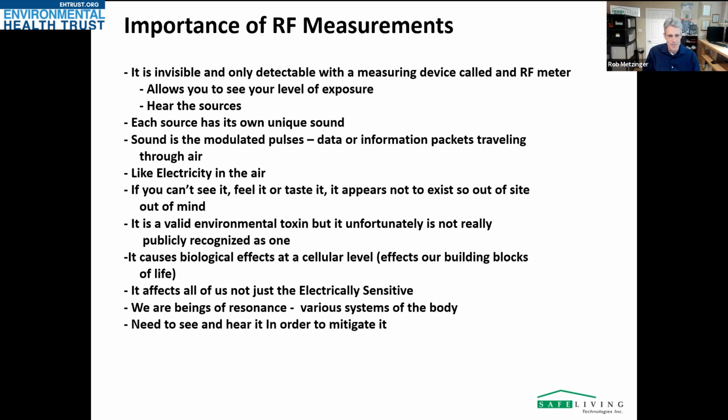So one thing we're big on is an engineering approach to this, which means you measure a source, you get rid of it or shield it, and you remeasure it. And it's really important to do that. Then you know for sure that you've got the source of the problem. So that's kind of the basis behind all of this, and behind what we do, and behind the products we carry as well.